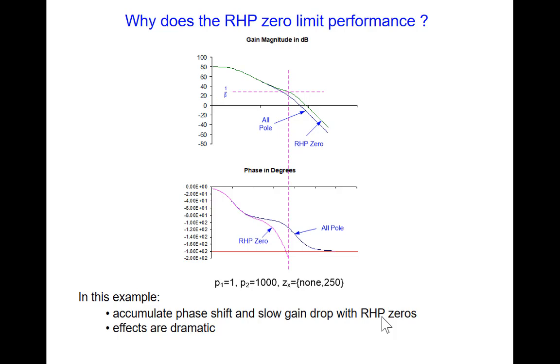So we see that the right half plane zero added additional phase shift, which had to be offset by increasing that compensation capacitor a lot to compensate for it. So that's what it does to us. Tomorrow evening we'll look at what we can do to remove those problems, to move that zero from the right half plane back in the left half plane. Any questions?